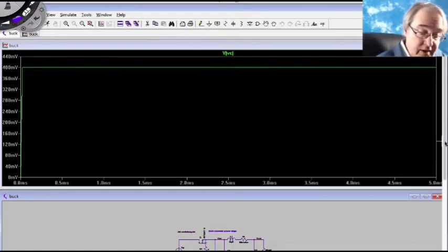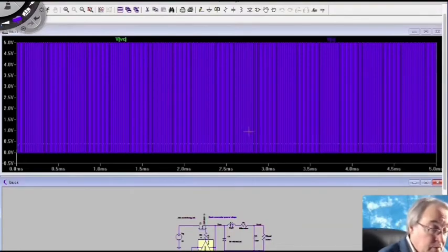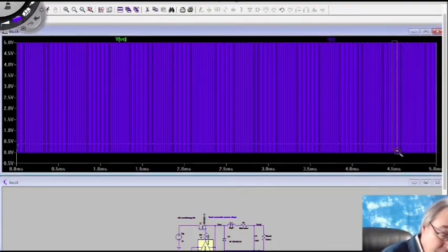We can look at the output voltage that the pulse width modulator makes. So I'll move the cursor over C. Okay, the blue signal here is switching up and down with a frequency of 100 kilohertz. Let's get the magnifying glass and zoom in on part of this, maybe over here.